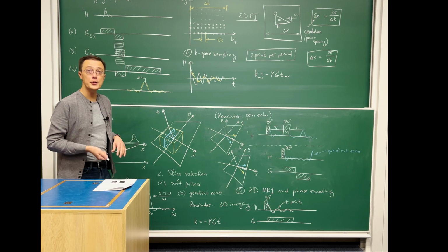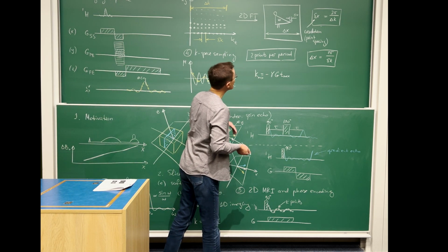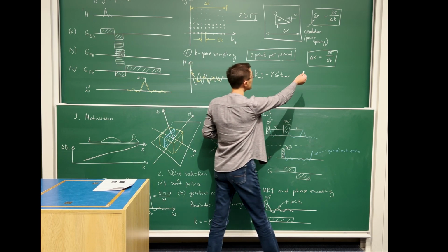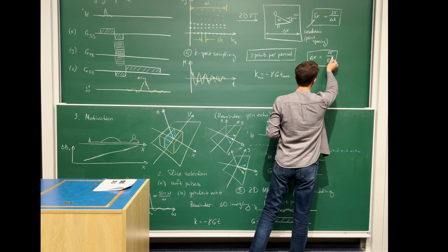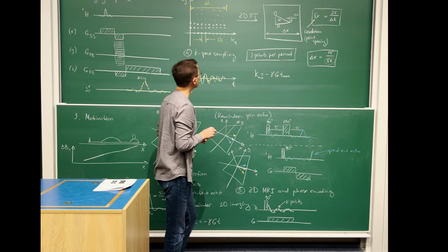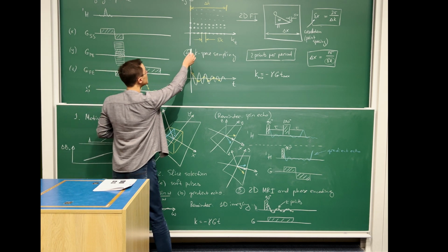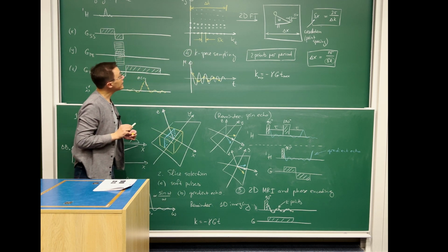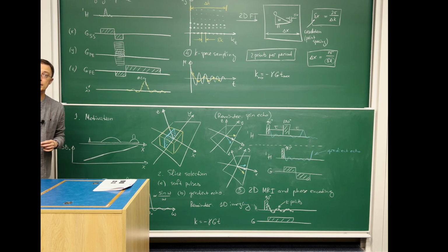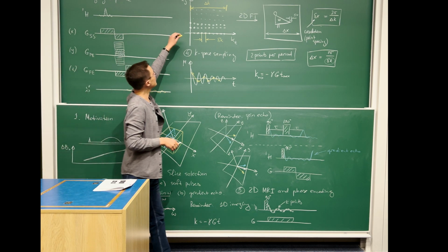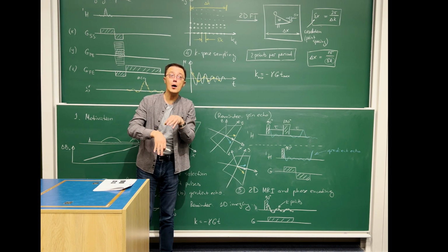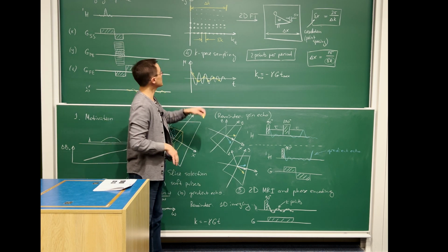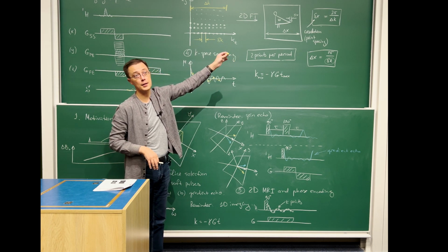So that is what determines the resolution. Then, of course, the size of the image, that's straightforward, right? We simply need to have more points acquired per unit time in the K-space, so we just need to make it denser, but that comes at the cost of sensitivity, because the digitizer runs at full throttle every time anyway, so it puts them very, very densely, but then it averages nearby points out to reduce the noise to the sampling levels that you realistically require for the size of your image.